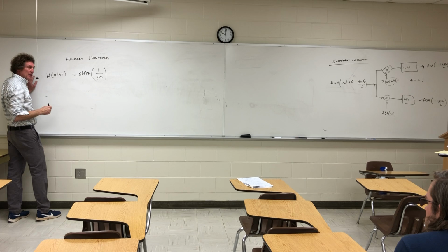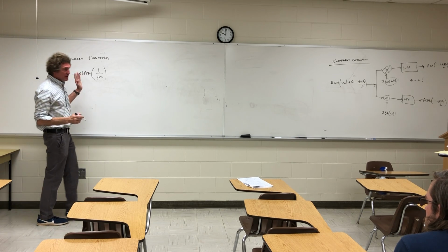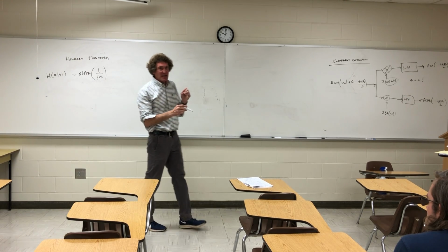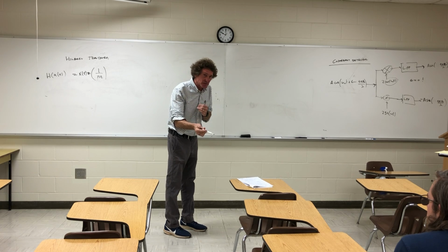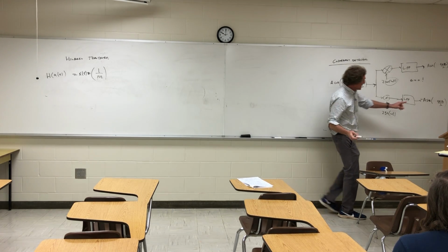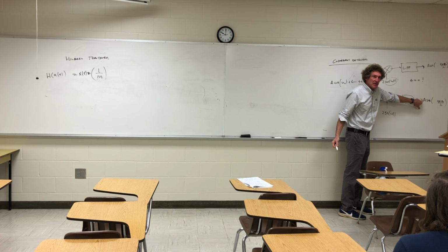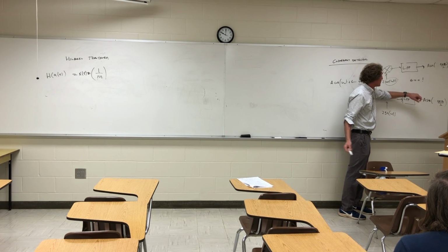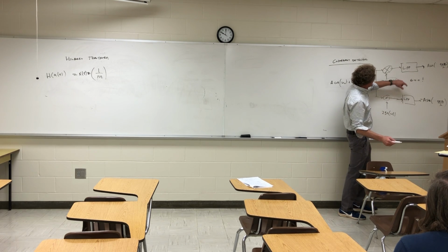Now why is that important? The Hilbert transform changes it by exactly 90 degrees. So the cosine turns into a sine, you see how that minus sign comes out? This component is usually gotten by taking the negative of the Hilbert transform of this right here.